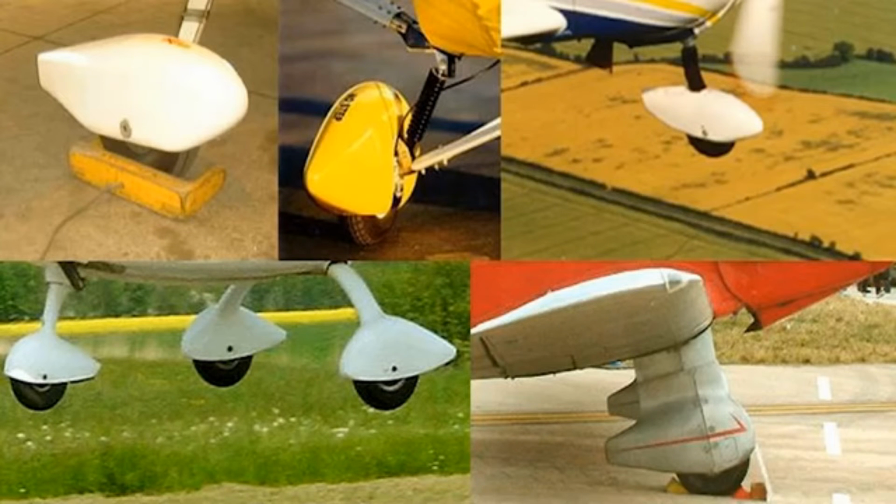One drawback to their use is the problem of them picking up mud when landing or taking off from grass airfields. This can add considerably to the weight of the aircraft and may affect take-off performance. To avoid this eventuality, if any mud has been picked up, the spats must be removed, cleaned, and replaced before the next takeoff.